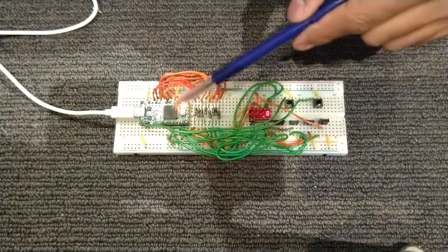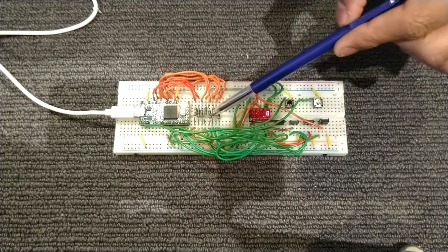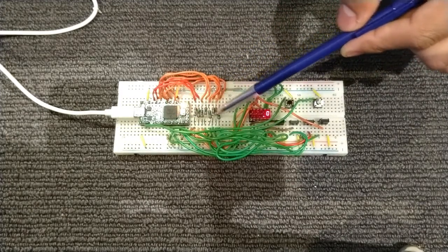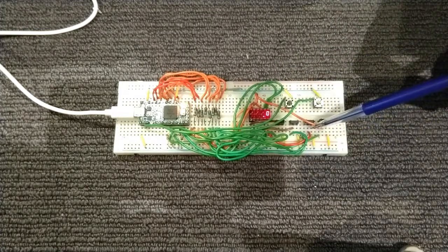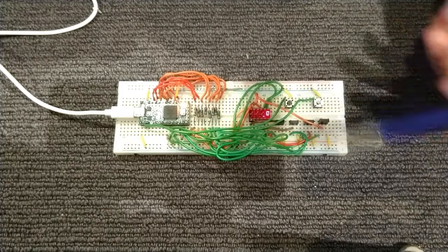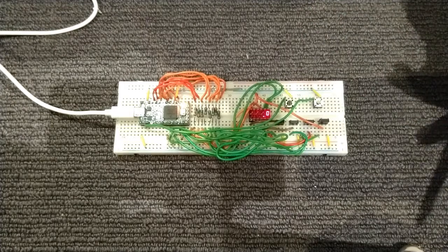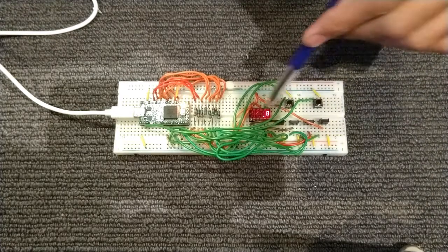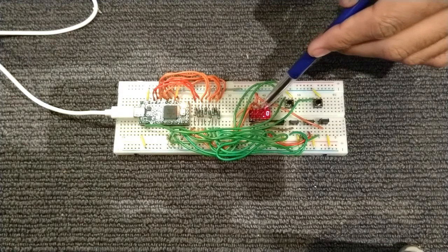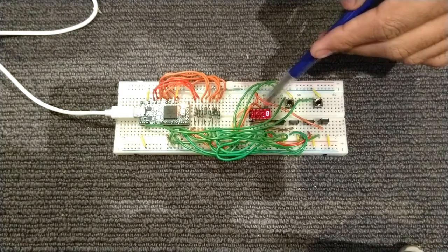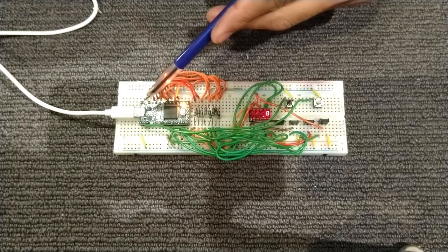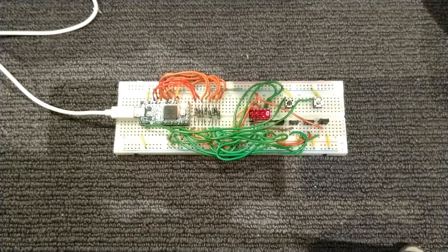And this is my hardware, and I have used, you can see it, a Teensy 3.2 board, 340 ohm resistors, bubble display, 4 MOSFETs, 2 push buttons, and a few jumper wires. Talking about why I have used 340 ohm resistors: for the full brightness of this LED, we need a current of 5 milliamperes, and we have a source of 3.3 volts. So by the calculation of Kirchhoff's law, the resistor is 340 ohms. That's why I used a 340 ohm resistor.